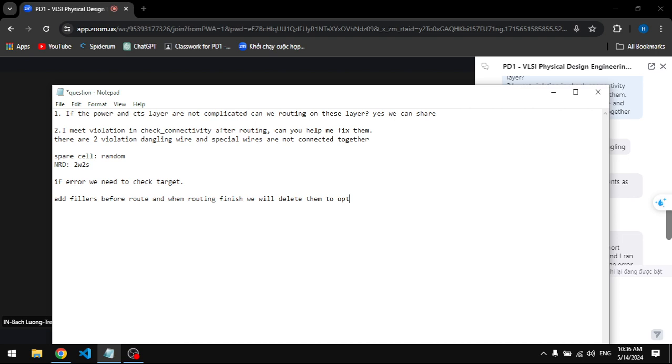If you don't want to see it, you can add a dash ignore dangling, of course. But you have to know what you're ignoring, because it's kind of dangerous. Don't just ignore because you don't want to see it. You have to validate that it is okay before you do a dash ignore, so it looks cleaner.